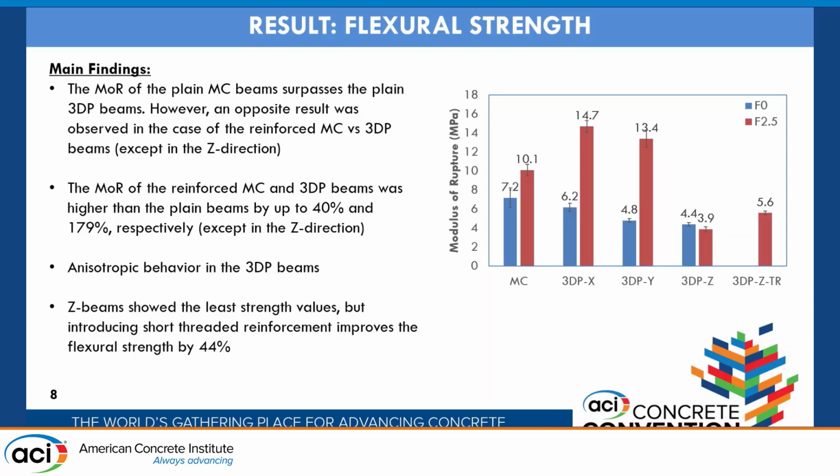So as a result, we have observed an anisotropic behavior in the 3D printed beams, and of course the specimen tested in the Z direction, which is parallel to the interfaces, showed the least performance. And interestingly, we also again confirmed that even when you use a very high dosage of fibers, you do not have any kind of structural contribution to the interface, right?